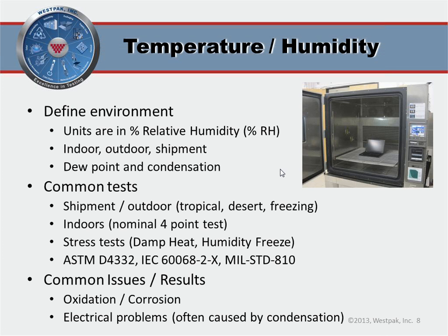Let's think about our laptop. You're in your nice air-conditioned house, have your cup of coffee, want to go outside and sit on the porch. Your laptop is likely below the dew point, and you may have a condensation problem occurring on the inside of your product. Lastly, there's no effective humidity below freezing.